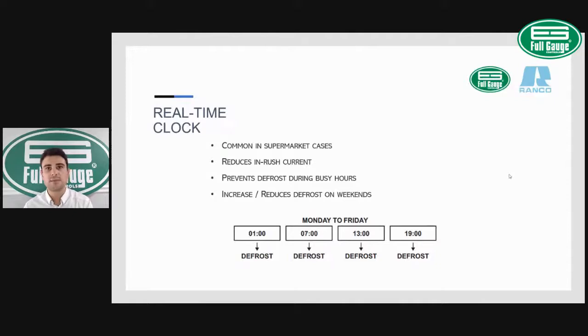And when the restaurant is busy, we know there is a lot of door opening, closing, people grabbing stuff out of the refrigerated space, putting warm stuff into the refrigerated space. So having defrost cycles during these busy hours is actually critical because your refrigerated temperature might increase. So that's the nice feature about setting a real-time clock defrost, is to allow each piece of equipment to enter defrost at a certain time.